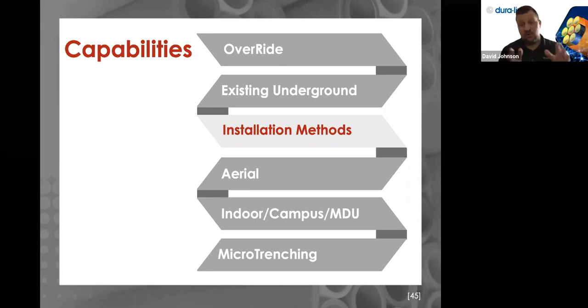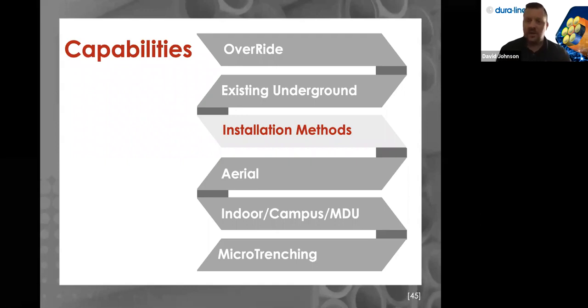That air helps float those and disconnect really those ducts as they're touching, it really helps them float around that cable. And, you know, HDPE has a natural less friction on it. There's just the way the material is made. It does kind of glide past that, where another fiber cable does. It's the way that the oversheath's made, doesn't have as much HDPE resin materials as our duct does. So it's got less friction over it. It does glide past that fiber a lot easier.